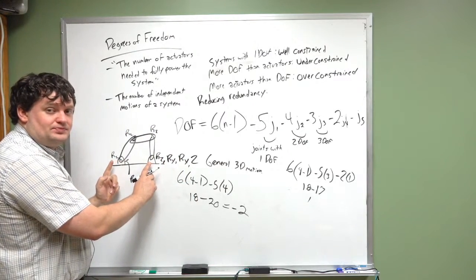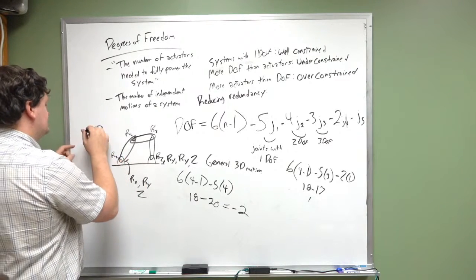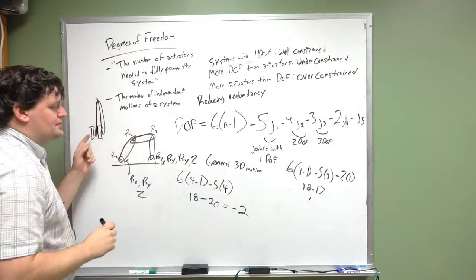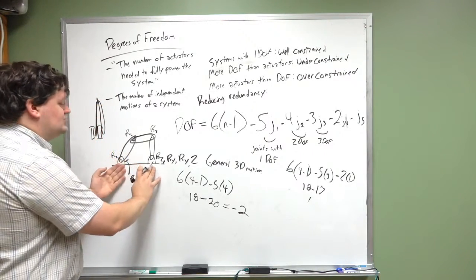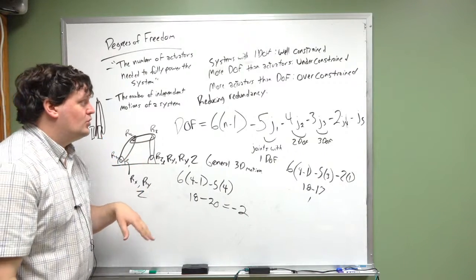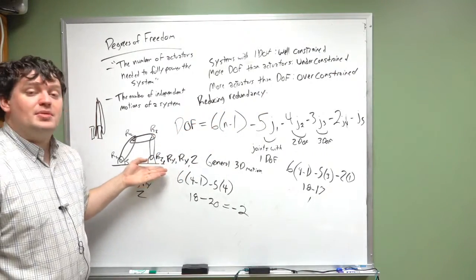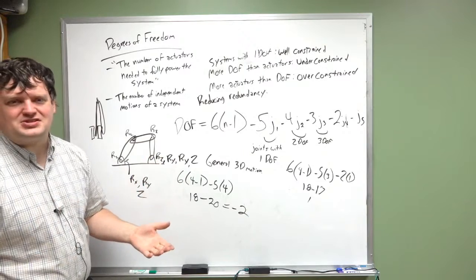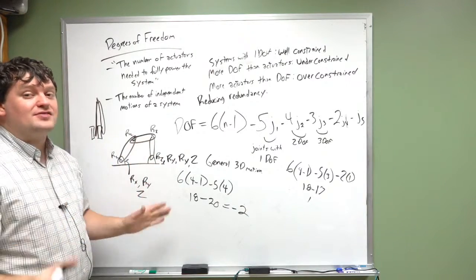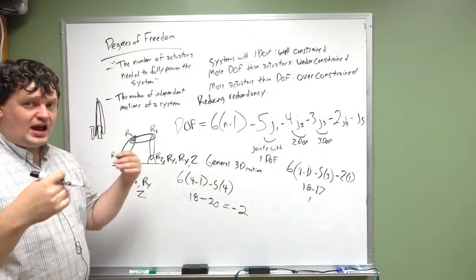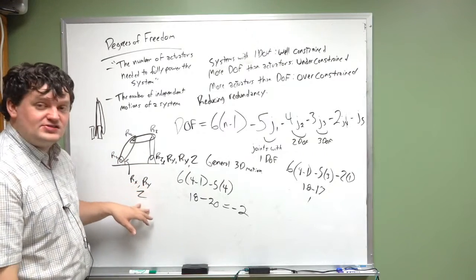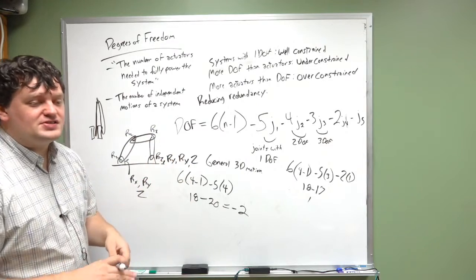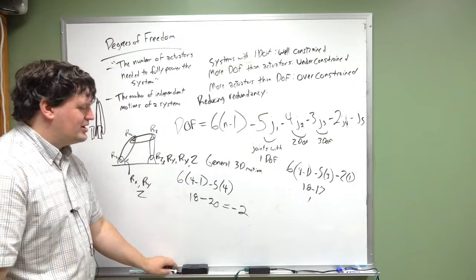If these two axles are out of line, the connection point here is here, if we're looking at it from this way, the connection point here is like this. This could cause the entire system to freeze just by having these two connection points out of plane with each other. Reducing this redundancy actually makes the machine move smoother. Now if you make sure that these are in plane, the 4-bar linkage ends up working just fine. Planar linkages are kind of the exception to this redundancy rule in that it's okay to have redundancy in the Rx, Ry, and Rz directions as long as the entire mechanism is moving in one plane. But you can figure out a way to do that in other places too.